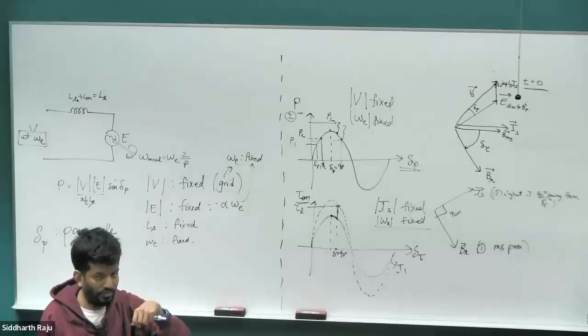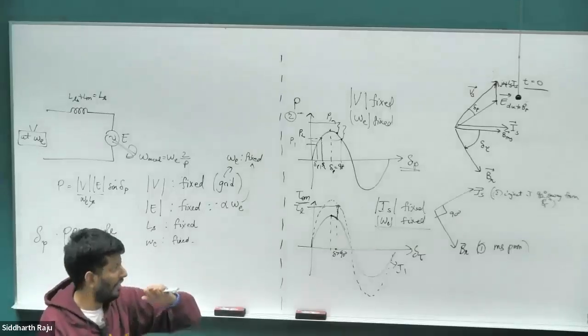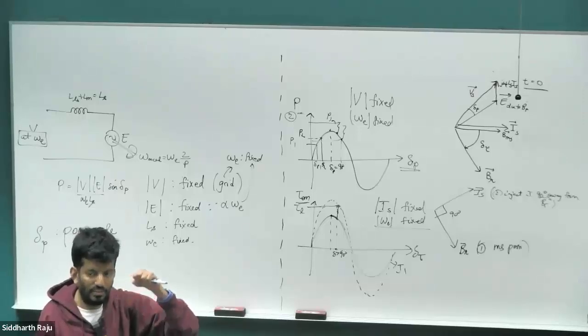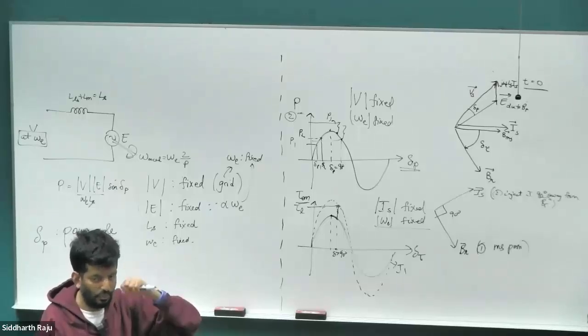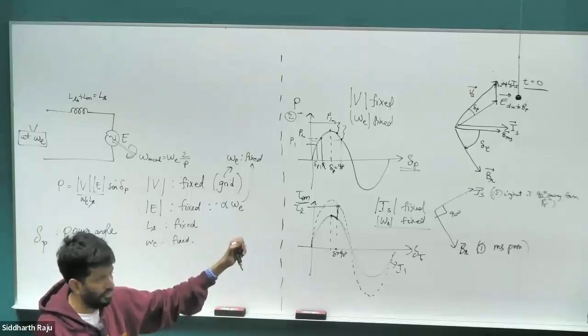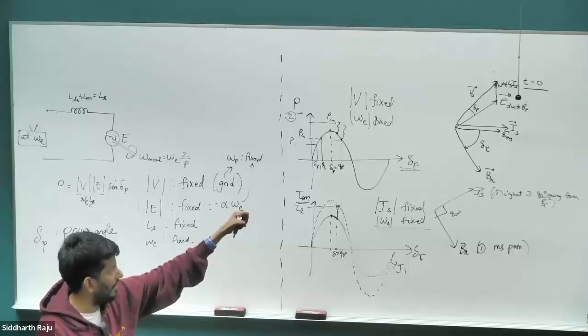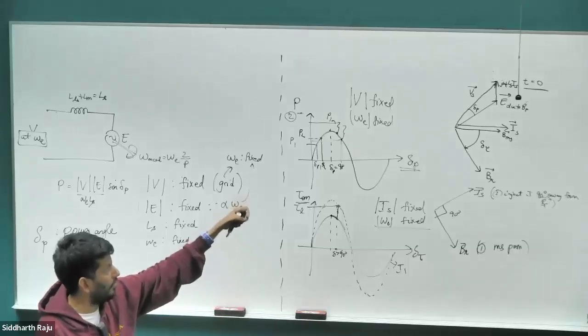On the electrical side of the generator, you put some load on it. It is basically going to ask for more power on the electrical side. And that power would initially come from the inertia. And then the machine would start to slow down. And then the angle would start to increase between the rotor magnetic field and the stator magnetic field, which would also then increase the angle between the EMF and the voltage V.